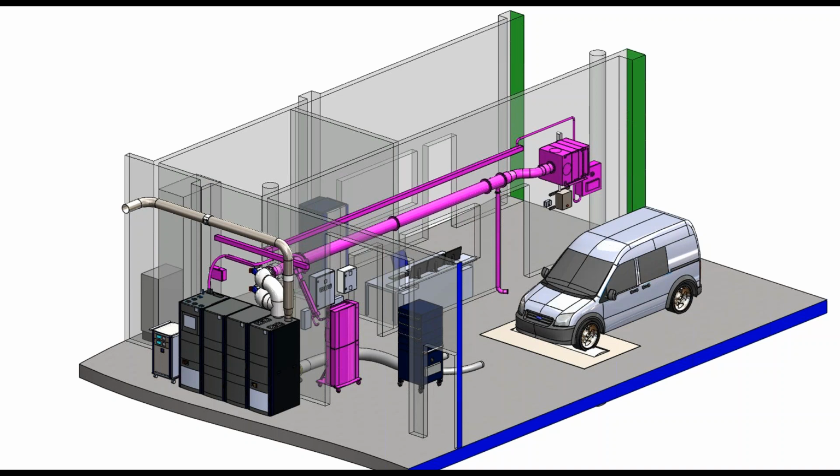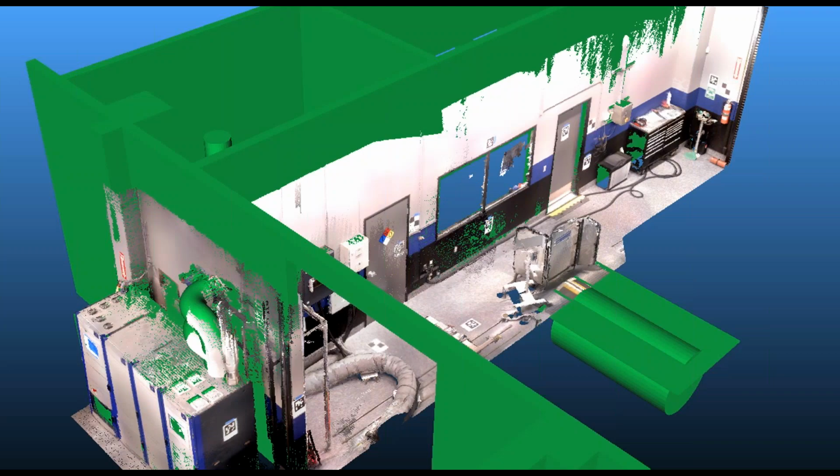There's something that got missed, where some pipes, some doorways were, where some existing equipment was, and they missed out on it. So what they've started to do now is they'll go and do a scan, a 3D point cloud scan of the existing facility. And they'll take this 3D point cloud scan and bring it back to their office and read it in and combine it with their CAD tool. So here you can see the green is sort of the CAD overlay of the point cloud. And they do this just to validate that the point cloud was correct.